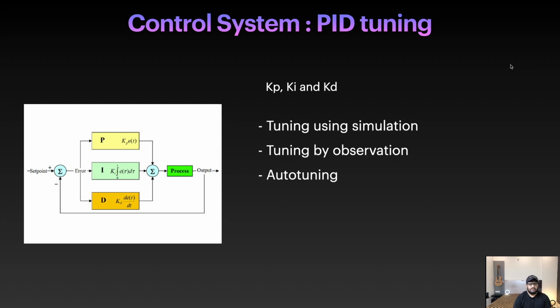So you log the data that at what particular instant, what command you gave from the transmitter and how your drone reacted. So based on that, you can bring that into the computer and you can see that, okay, I have given my drone command and it takes 2 milliseconds to react. So it's a high delay, and you increase the KPs, things like that. And you also observe that, okay, now my drone is having vibration on your axis, so you can dial down. So this is another method which I used to do a few years back.